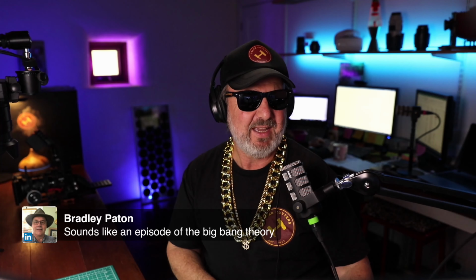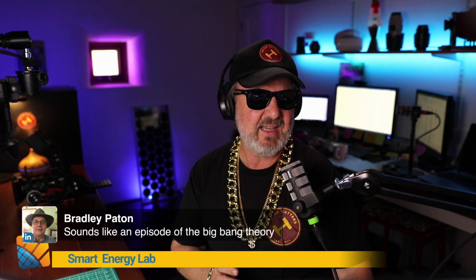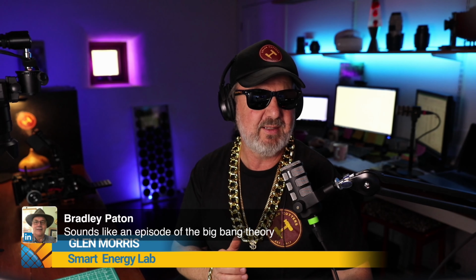Thanks very much. So it's all about string theory today and understanding how to consider when you need to have string overcurrent protection. I often talk about things on Toolbox Tech Talk that came up during the week, and this is one of them. I had some questions from previous students about string overcurrent protection, and they raised some interesting side issues as well, which we'll talk about: array cable sizing and short circuit rating of PCE or inverters or charge controllers.